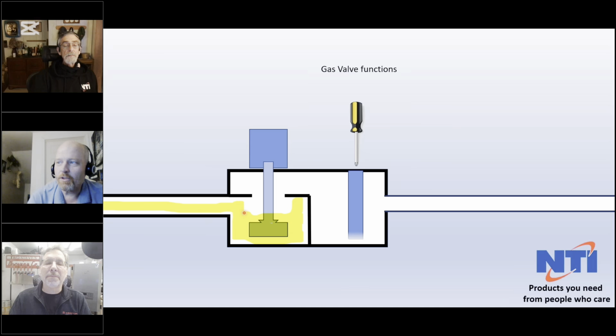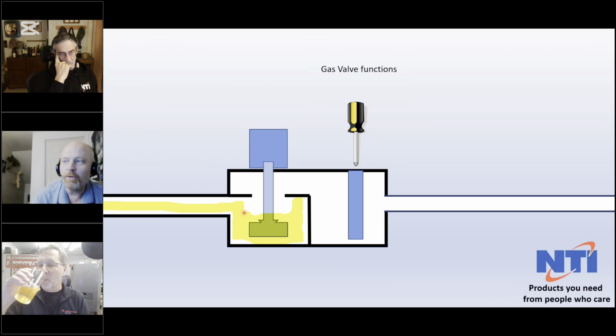So another option, of course, is to put in an adjustable gate valve. And this is my simulation for the type of gate that's actually in the valves that we use. It is very literally a gate valve at the outlet of the valve. When you tighten that screw, you're pushing a gate across the outlet, which is kind of like an adjustable orifice.